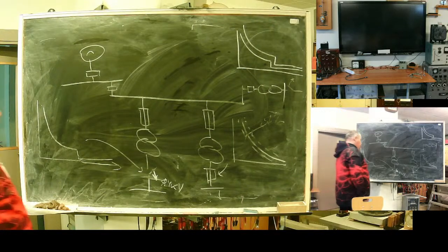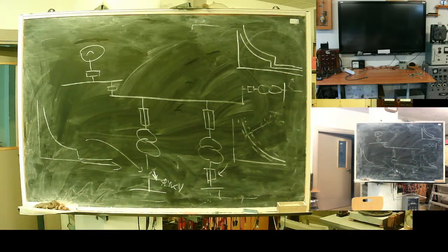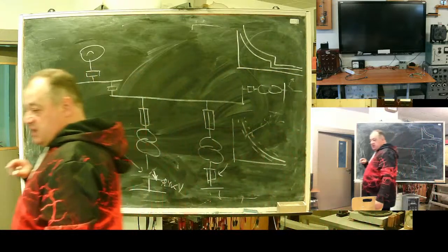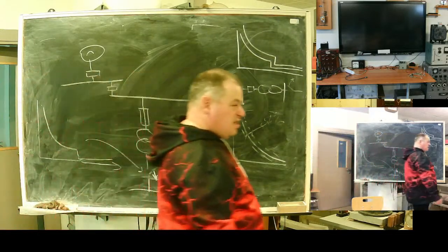Maybe in the old times, relays with a pneumatic chamber were popular, some manufacturers very much loved relays with a pneumatic chamber. It has a chamber, piston and a calibrated nozzle. On small currents, this chamber collapses slowly. On high current, the higher the current, the higher the pressure, the higher the air flowing out speed.